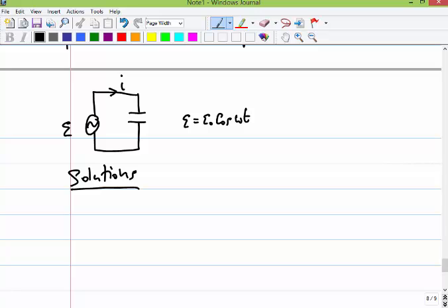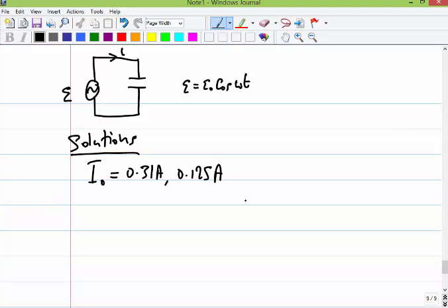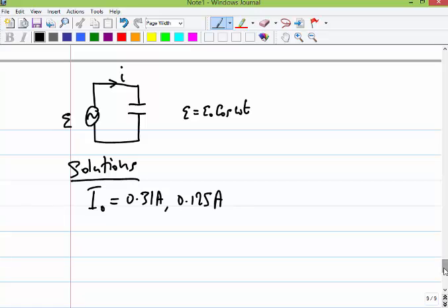Okay, let's look at the solutions. What do you have for the current? I'm pretty sure mine's wrong. I got 0.3142. Okay, let's see. Peak current, 0.125. What do you have? 0.1256. Okay, you got 0.31 and then 0.125. So let's write both of them. Remember that we had a peak current equal to the voltage over the resistance. In this case, the voltage is just the peak voltage across the capacitor, and the resistance is the capacitive reactance X_C.